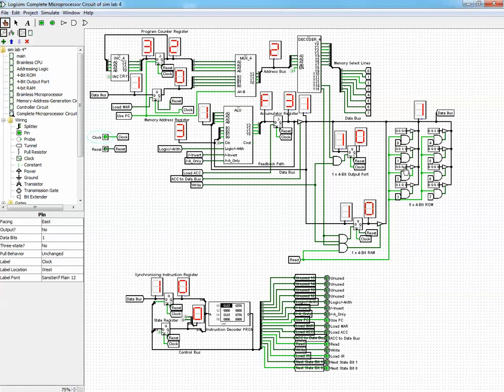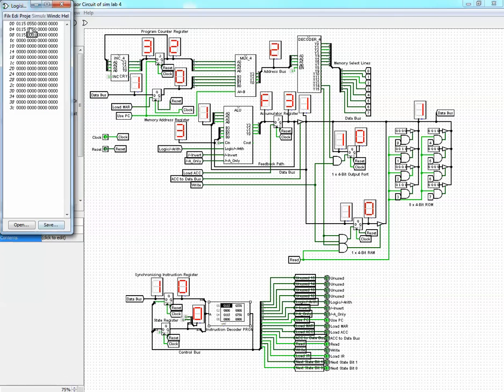Why did I store here a 1? Because I know a priori that the 5 and the load command, the 5 is in the third micro instruction, and the load command and the addition command are in this row, and this row corresponds to 0001, which is this 1 exactly.